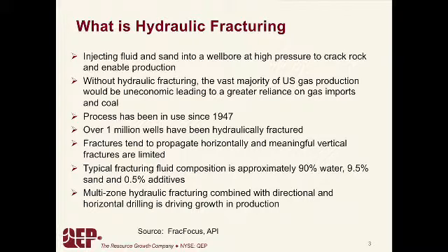The fluid composition, we've already heard, is mostly water and sand, with a small percentage, usually about 0.5% or so, of additives, and those include things like soap, antibacterial agents, etc., as well as, in some instances, guar gum, which is the same stuff you find in toothpaste and in some cosmetics, to help carry that sand into the fractures. And so it's this marriage, as I pointed out earlier, of hydraulic fracturing along with directional and horizontal drilling that's been the real key to unlocking a huge renaissance in the oil and gas industry in this country.